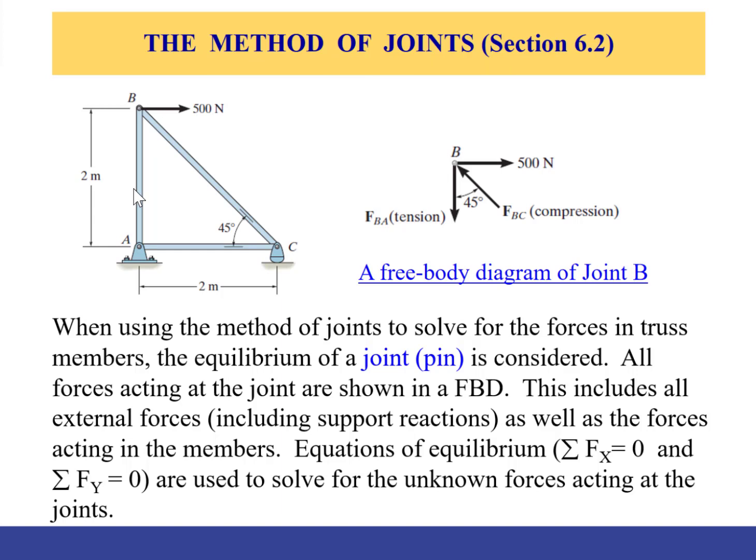First, we assume that each beam is either under compression or tension, and for simplicity, we're always going to assume that each beam is undergoing tension, meaning the beams are being pulled, which will exert a reaction force at the joint to oppose that pulling action. So they will be in the reverse direction.